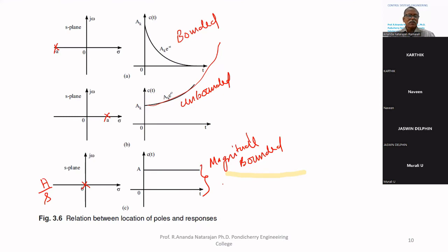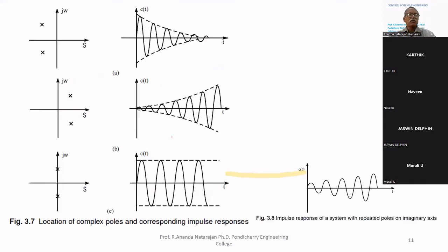These are all real poles, no oscillation. If we take a complex pole, 2 poles are there, second order system, left hand side, it oscillates, but finally, for impulse input, all are for impulse input, not step. Impulse input means giving a blow, giving a punch, that's all. After that, initially it's at rest. If we give a punch, it oscillates, finally it comes to rest. So it is a stable system.